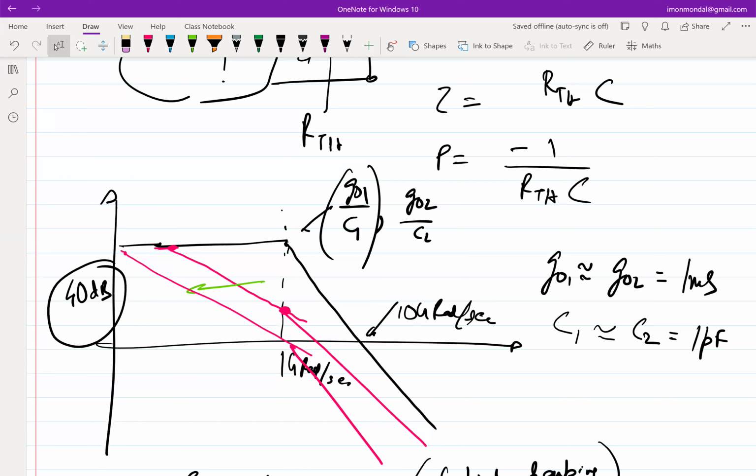But in an integrated circuit, the capacitances are extremely costly. When I say costly, I essentially mean that they take a lot of area. And the area is directly proportional to the size. So a 1 nanofarad capacitance will be like 1,000 times costlier than 1 picofarad capacitance, for example, in terms of the area it takes. So as it turns out, you cannot even make a 1 nanofarad capacitance in an IC. It's so big. It will take up the entire IC, 1 nanofarad capacitor.